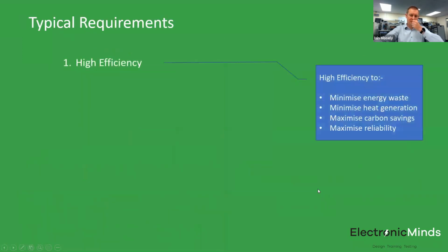Okay, so I'm going to talk mainly about that box of electronics. Whether it's an AC charger, that box of electronics sits on the car. If it's a DC charger, it's in the charging station. Both of them are doing roughly the same thing. They're converting a power source, normally three-phase or single-phase AC, and they're turning it into a high-voltage DC supply to charge a battery. And there are certain requirements you would like to have that system meet. Obviously, high efficiency is very important.